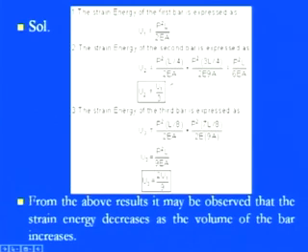So U2 is, first, for the L by 4 length in which the diameter is d, P squared L by 4 over 2 into E into A. Here A is for a uniform cross-sectional bar, pi by 4 d squared. But in the other term we have the 3d diameter, so obviously the area is 9 times the previous one, and the length is 3L by 4. So we have P squared 3L by 4 divided by 2E times 9A. If you compute those, we get a total of P squared L by 6 times EA. So if you increase the diameter, the strain energy stored is 1/3